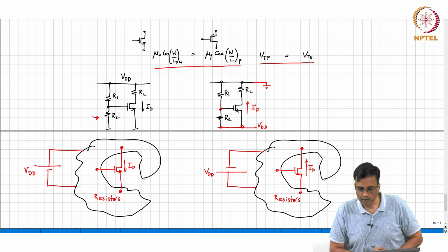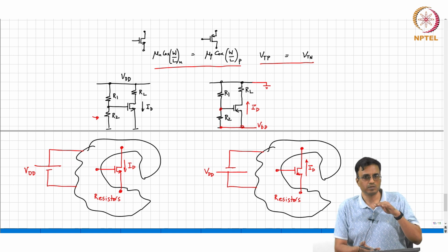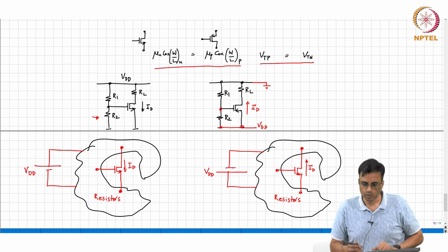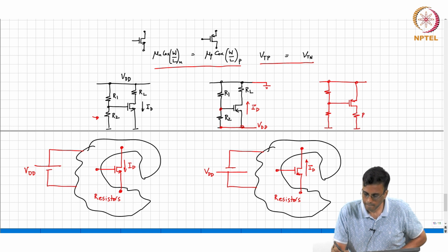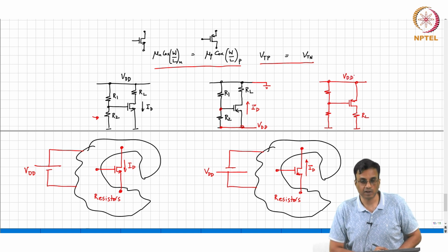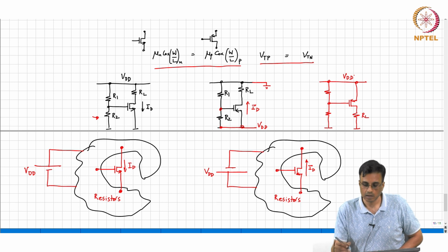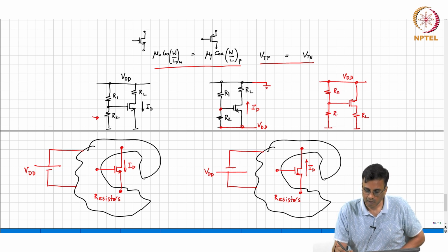Okay. All right. Now, what is something else that we don't like? The higher potential is below and the lower potential is above. So we don't like that. You just redraw the circuit so that VDD is on top. That is RL, this is VDD. What must be the upper resistor in the bias network? R2, and this is R1.